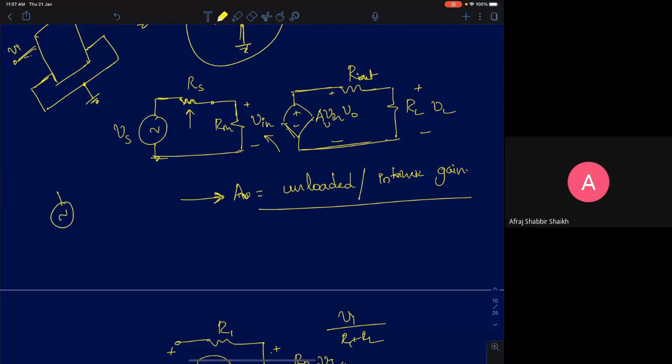Let's say, for example, a microphone: what I'm speaking right now is converted to an electrical signal by a microphone. Let's say you are a circuit designer and you are supposed to design an audio system. What will you do? You are going to model your microphone as a voltage source. But this model is absolutely incorrect. Why is that? What is the problem with modeling a microphone as a voltage source? So the maximum power delivered by a microphone is very small.